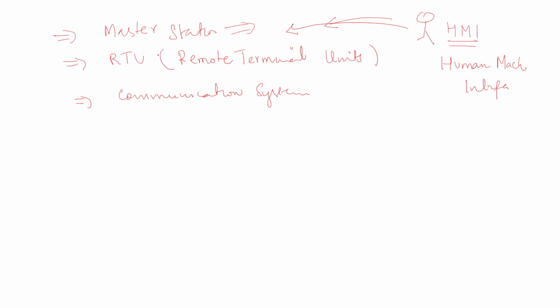Another term which I wrote over here is remote terminal unit. Actually it is a microprocessor based device which interfaces with a SCADA system, by transmitting the data to the master station and changing the state of the devices by receiving the control messages.